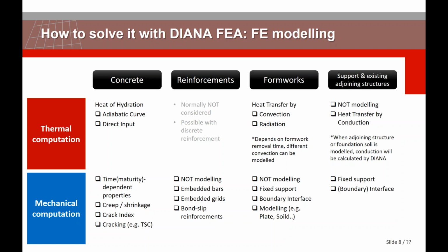this aspect. We can start from thermal computation for concrete. We support heat of hydration input in two ways. The first one is the adiabatic curve, direct input. And the second one is that you can directly input the thermal characteristics of your concrete. And the reinforcement normally doesn't do anything. If you really want to consider heat transfer internally in your reinforcement, you can do that, but normally we don't do it.